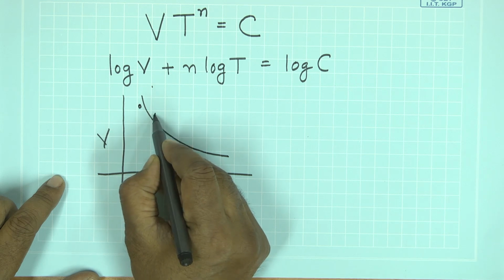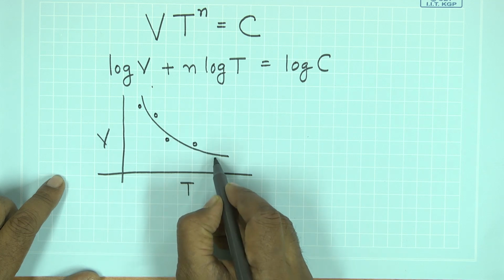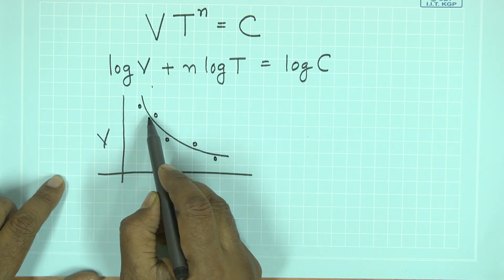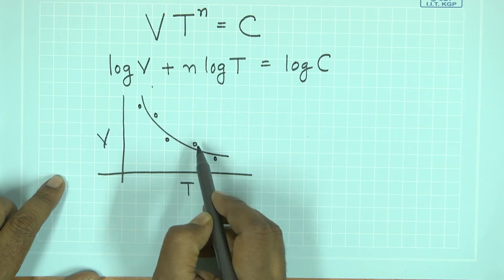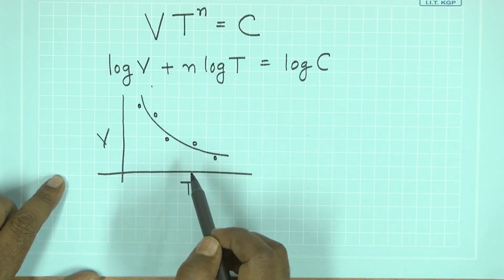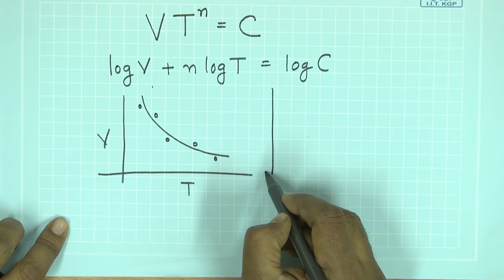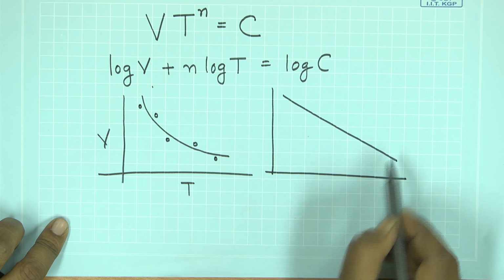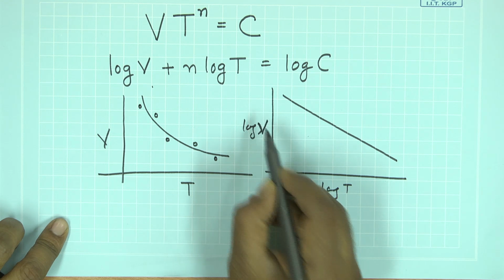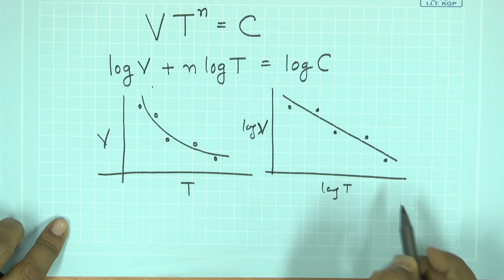we are saying that in the practical case, in real life situations, all these values of velocity and tool life combinations have every chance of not falling exactly along a particular relation of this type, v into t to the power n is equal to constant, but we can have a least square fit. So, we turn to the log paper and we get a straight line representation for log v, and therefore these points which are experimentally obtained again appear this way,